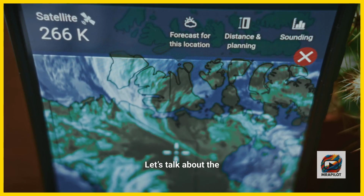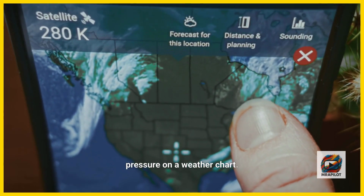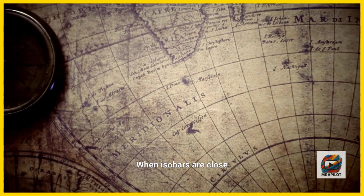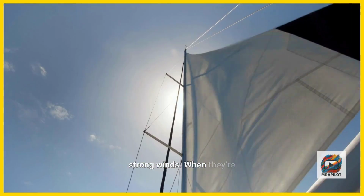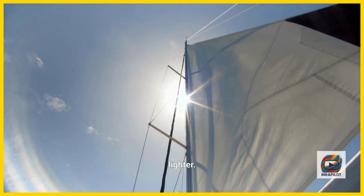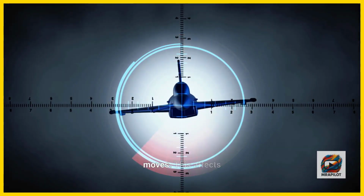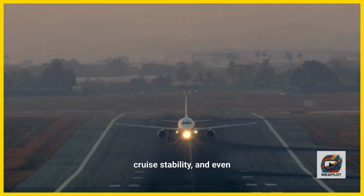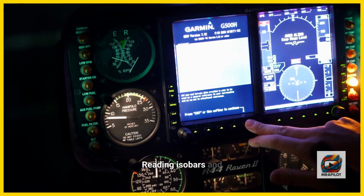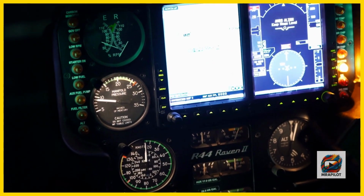Let's talk about the isobar pattern. Isobars are lines of equal pressure on a weather chart. When isobars are close together, that means a steep pressure gradient, which results in strong winds. When they're spread out, winds are lighter. The steeper the pressure gradient, the faster the air moves. This affects takeoffs, landings, cruise stability, and even fuel consumption. Reading isobars and estimating wind strength is a fundamental skill for every pilot.